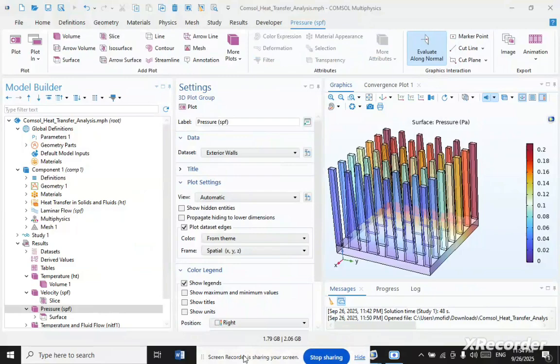Among various innovative techniques, the microchannel heatsink has gained much attention. Furthermore, the micropin configuration of the microchannel has yielded better performance than the conventional microchannel due to greater convective area, secondary fluid flow, unique vortex production, and also thinner boundary layers.